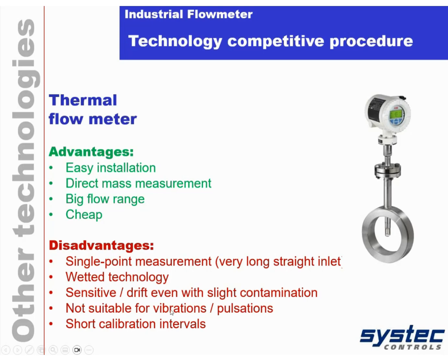So they are also not suitable for pulsations. We know this from engine test beds where Systec is doing a lot of work. If there's pulsation coming back from the engine, the readings are not correct. And you need short recalibration intervals, in particular if you have not perfectly clear gas.